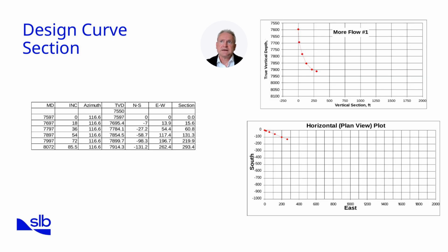The plot shown here is a TVD versus vertical section profile with no azimuthal turn, as confirmed by the survey listing. This highlights the importance of kicking off in the correct azimuthal direction. A poorly selected kickoff direction may place the well on an azimuth far from the planned target, requiring large corrections later. As inclination increases, the dogleg required to turn even a small amount grows significantly. Therefore, it is best practice to perform most azimuthal corrections early, while the hole is still close to vertical. This results in smoother geometry, less torque and drag, and a more drillable trajectory.